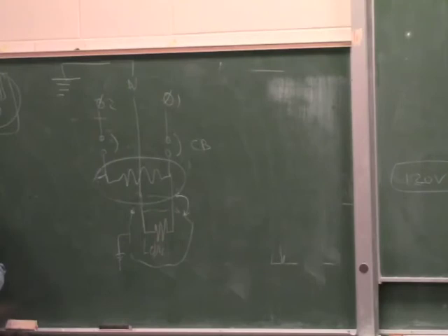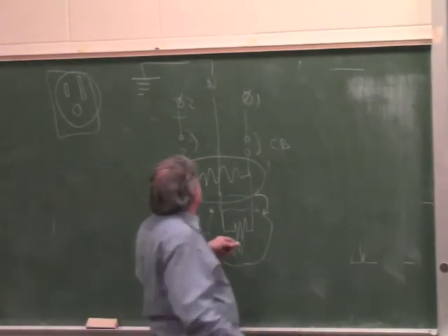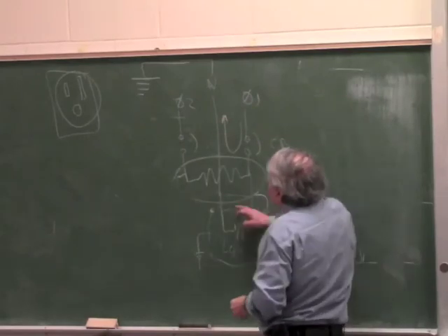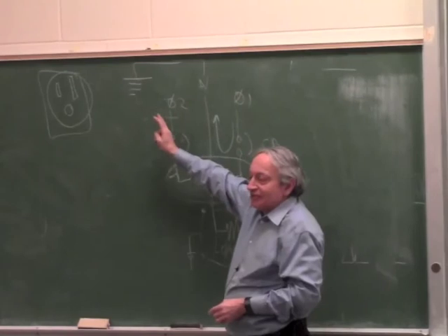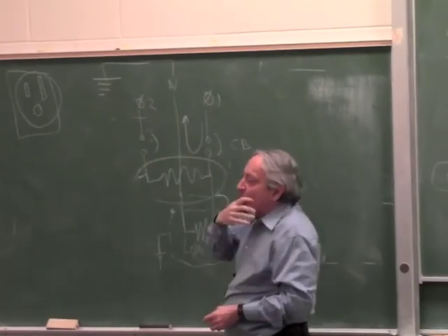Good? Okay. Now, what that means is that all the return currents in a house, coming through the phase, return through the neutral, or coming through a phase and return through the opposite phase. So there should be no currents in the ground. But there is always some leakage.